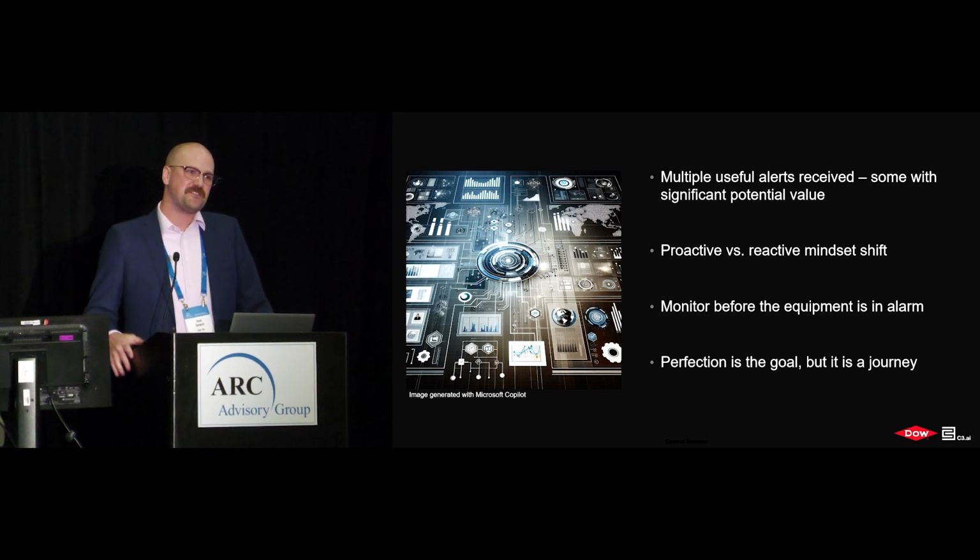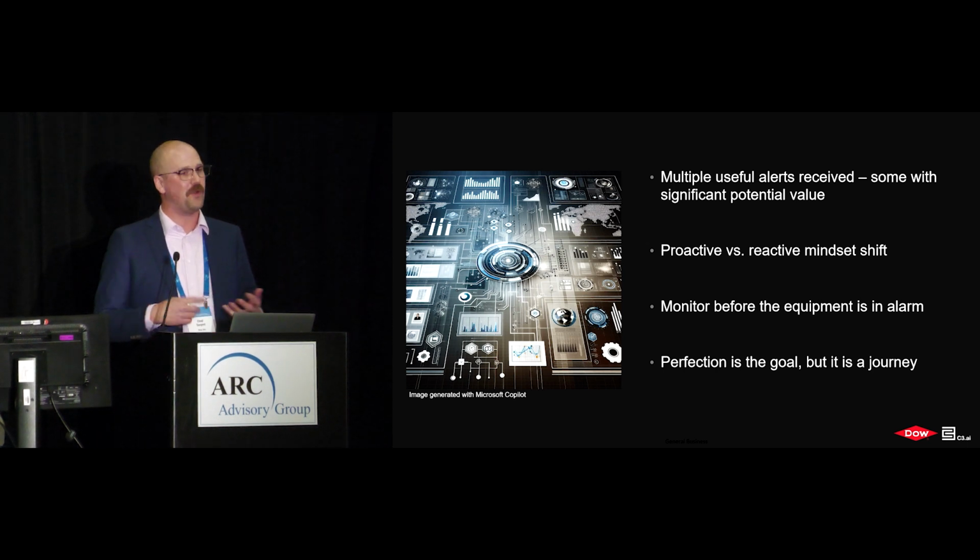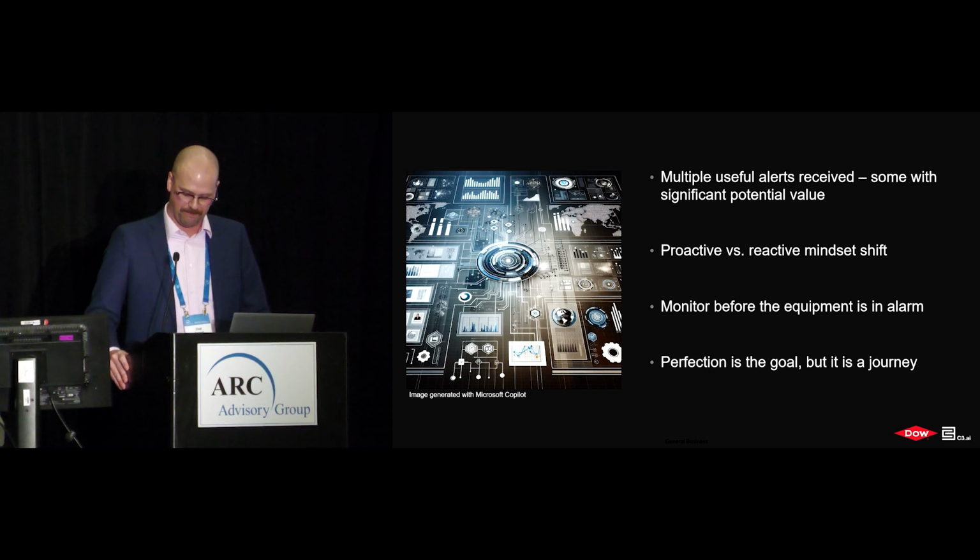We've also had it detect analyzers that are providing results that are starting to drift. And so it allows us to perform a calibration before those drifting results result in automated actions that are undesired or alarms to the control room. Historically, we rely on our production engineers, our technical advisors, and our operators to monitor trends and identify these potential issues. So we're very reliant on their experience so that they know where to look. Now, rather than relying solely on that experience, we have this application that is monitoring and pointing them in the right direction much more quickly, I would say. It also helps new or less experienced individuals become effective much more quickly.